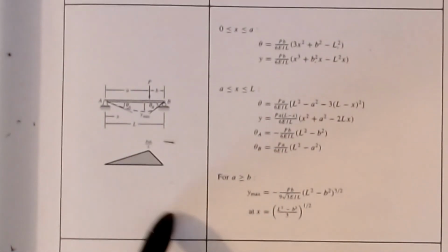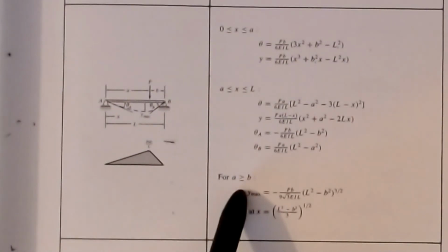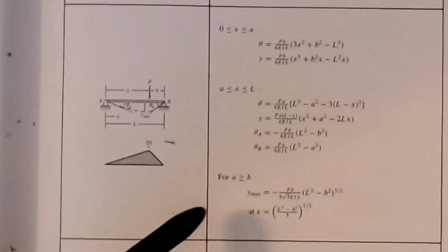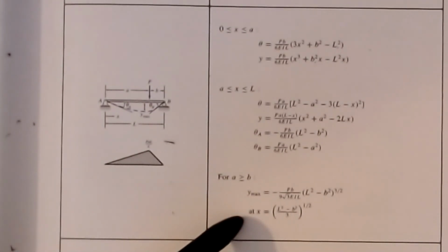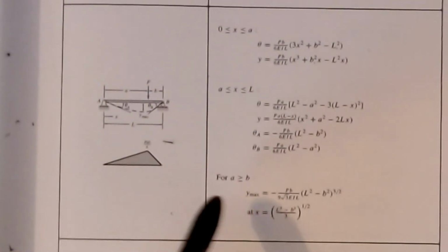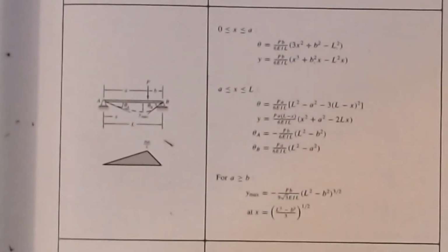for calculating this. But then when a is greater than b, they actually give you some shortcut equations for things like the maximum displacement, and it would be this equation, and its location of maximum is not necessarily underneath the point load, it's off center because of the curvature of the beam. In some cases they even give you the y max function. Now I'm going to warn you, and we'll talk about this in a little bit, that y max is a little dangerous to use unless you're absolutely sure that you only have one beam, or one load case, such as a point load on this beam, and these equations work, it works without a problem.